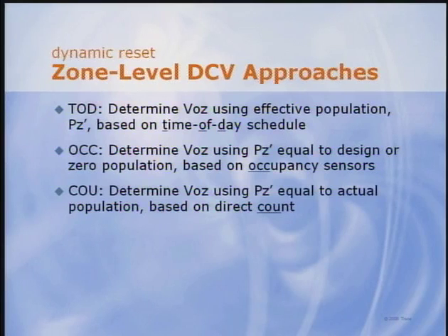theaters, for example. However it's determined, the ventilation system controller uses the current zone population to solve equation 6-1 for the zone outdoor airflow currently required. Then the controller can take appropriate action, which usually means opening or closing the outdoor air damper.